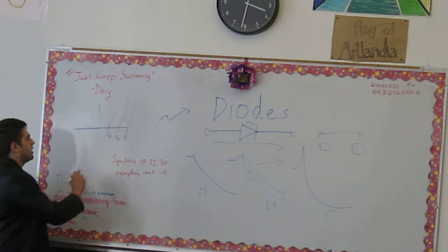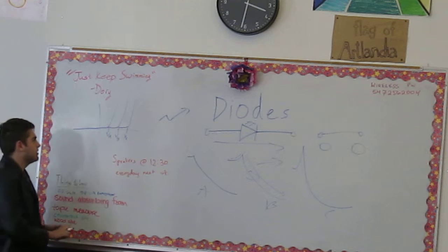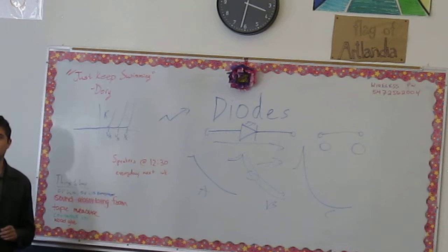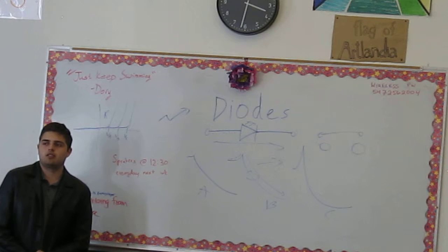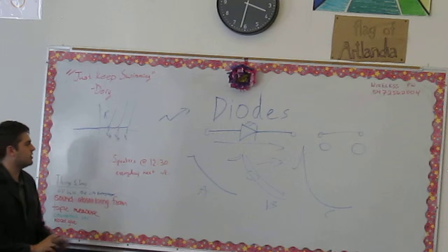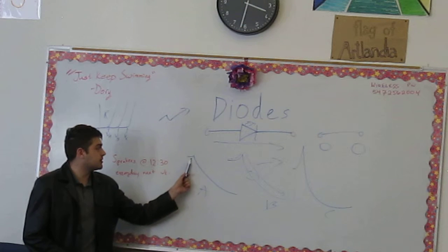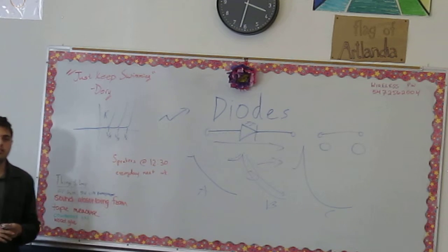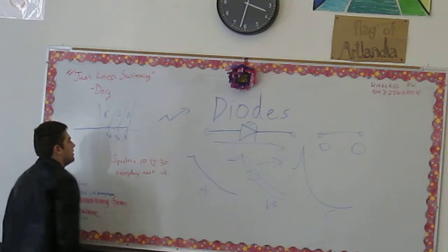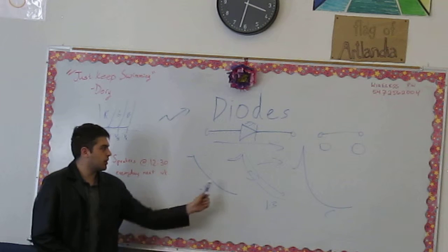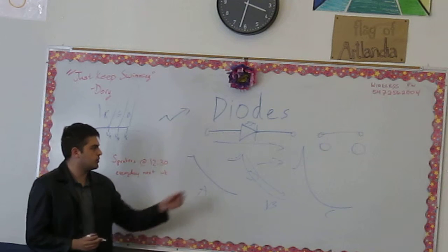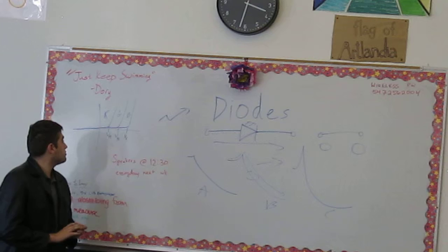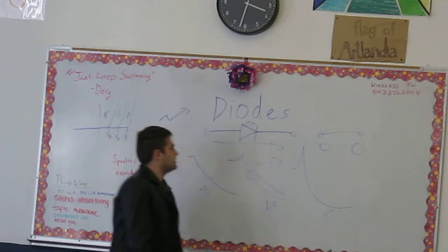Right. So, within the scope of red, green, and blue, because really it would be like IR, right? So red turns on first because it has the longest wavelength and the least amount of energy. Yeah, exactly. So it takes the least amount of energy. In order to get those long wavelengths, it doesn't take much voltage to send those photons on their way. The next one that would turn on would be what? Green, yeah. And then blue, right? So if you're looking at 3 different graphs and you have to match these to 3 different LEDs, you would look at their color for the voltage, and you would look at their brightness for the current. And that's basically what's going on with LEDs and diodes.